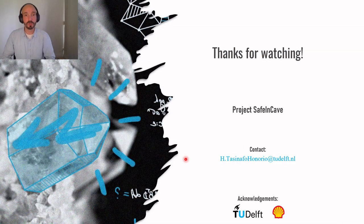Okay, so to close this presentation, we have discussed here the mechanical behavior of salt rocks. I have shown the macroscopic overview of how a salt rock behaves under certain stress conditions. We have shown transient creep, steady state creep, tertiary creep, and reverse creep.